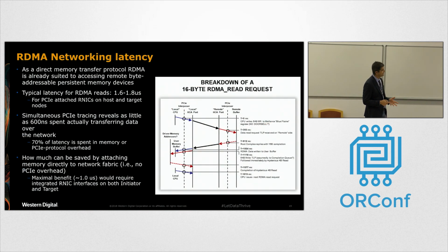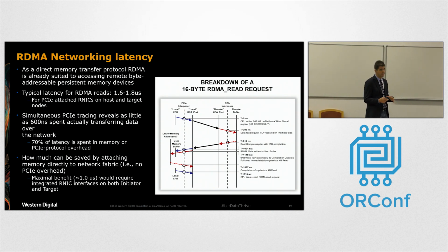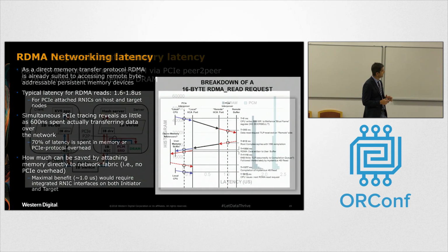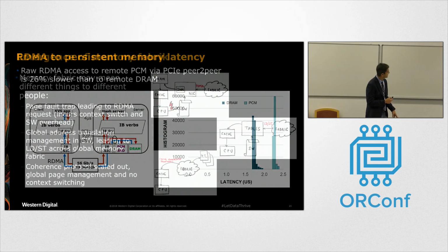I don't have enough time to talk about RDMA, but we did this very seriously in ADGST, and we were able to build nice demos using Mellanox hardware and our own phase change memory PCI Express cards. We've been able to use RDMA to get about two microseconds, you can see it on this chart. Whether we build these remote memories with DRAM or with PCM, we were getting between 1.8 and 2 microsecond latency. Not bad, not quite memory just yet in terms of the actual latency.